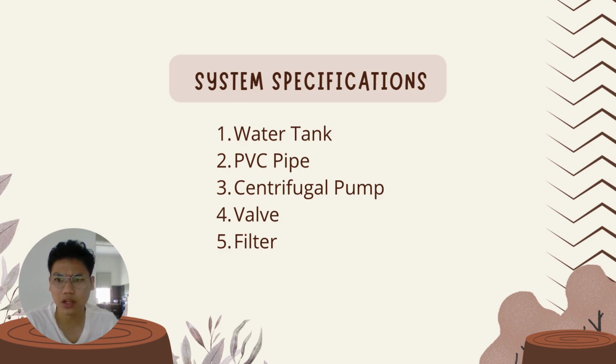For example, impurities such as sand, leaves, and sediments can damage or clog the pumps and downstream components. By preventing this material from entering the system, the filter helps to protect the pumps, reduce wear and tear, and prolong the lifespan of the entire system.